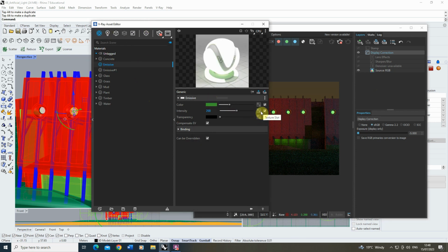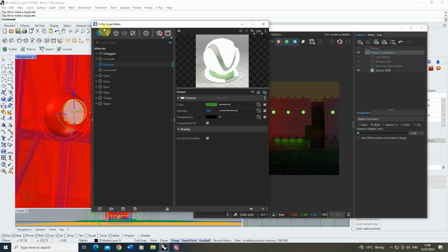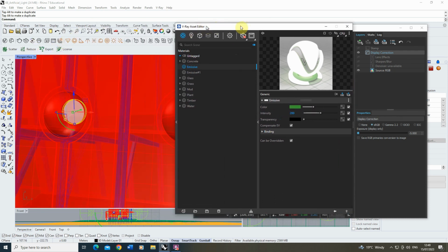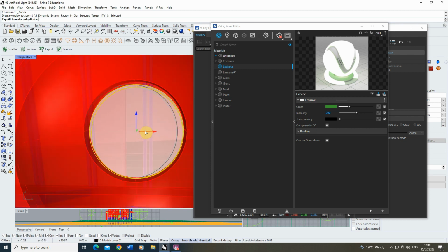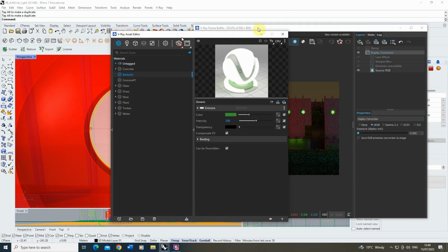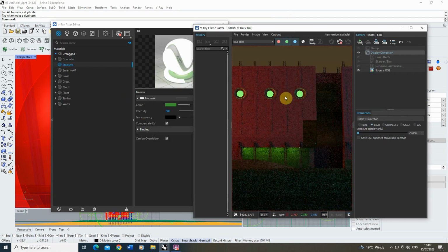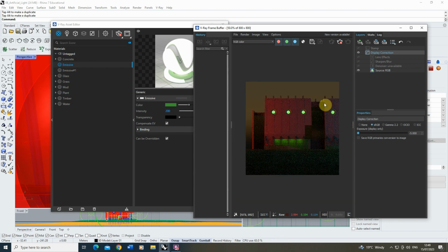So you can make these any pieces of geometry you want. You can tweak them as you go as well and change each of these properties you have in the objects. So you're not just limited to the lights that VRay has on offer. You can also create certain objects with different material properties as well as the lights we're using. Now, one thing that's quite good when you've got direct lights in the scene like this and you want to start to play around with their emission and how they're looking in the scene is actually to give a little bit of glow to these pieces.